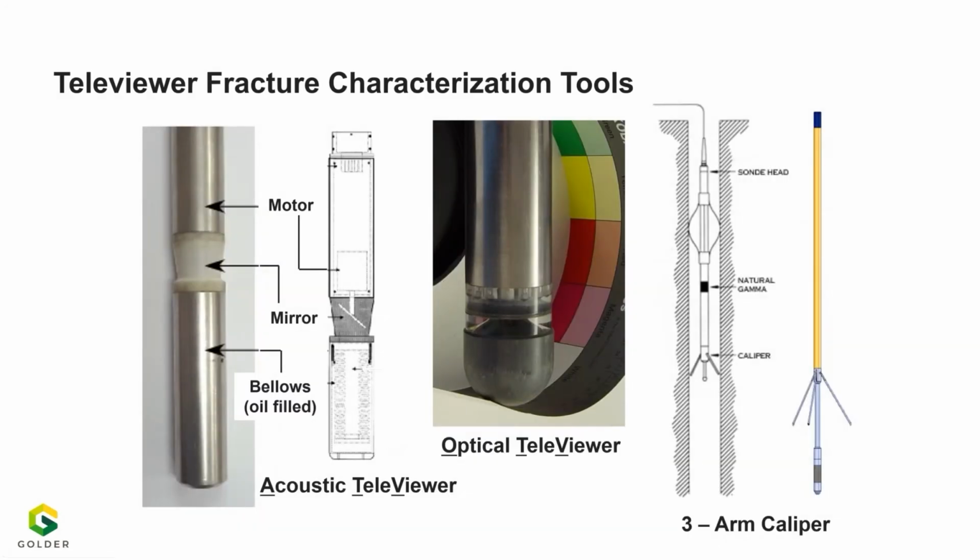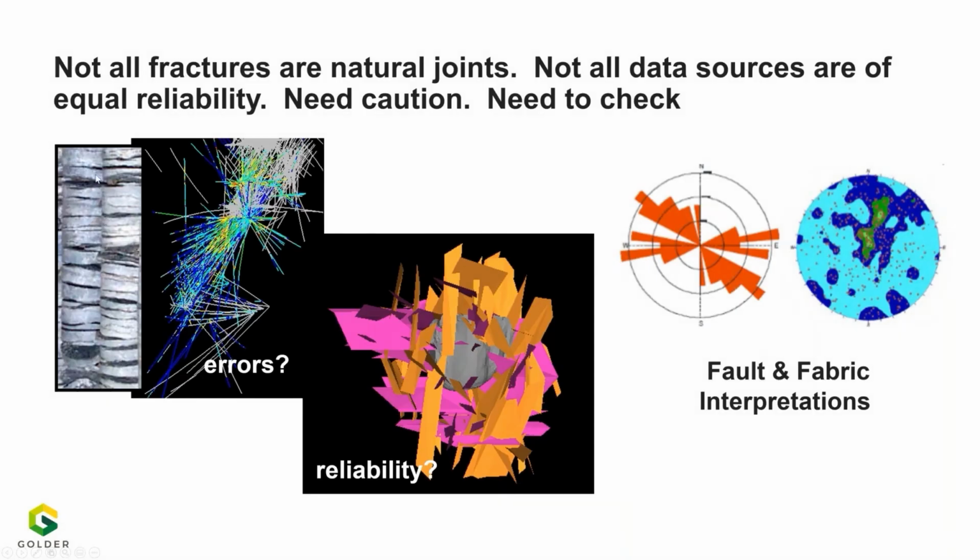The Televiewer can help, but again, we have to be a little careful because most of the Televiewer information used a magnetic orientation. So if you're in an iron ore deposit, be careful. Sometimes people log core and they log the fractures that are shown here as geological discontinuities. This is stress disking, and it shouldn't be plotted in your StereoNet, but I've seen that develop as a set within the StereoNet. We must be careful.